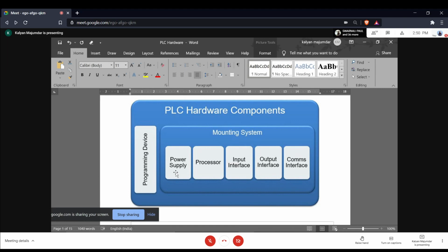Then, of course, the processor also includes memory, just like you can choose the amount of memory. The memory here is RAM and non-volatile memory. Non-volatile memory is always flash memory, exactly the same way it is in a smartphone. You don't have hard disks in a PLC. It's essentially flash memory, solid state non-volatile memory. So again, just like in a smartphone, you can say I want 32 GB, I want 64 GB, depending upon your requirement. You can further expand that using an SD card. All the options are equally valid in the case of a PLC as well.